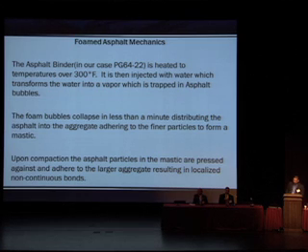Okay, so foamed asphalt mechanics. The way it works is your transport truck comes in with your PG binder, in our case 64-22. It comes in at above 300. Temperature varies. In this case, it was 325. We test the foam bubbles, just like I mentioned. Test your expansion rate, test your half-life, and then these particles are compacted, pressed, and adhere to larger aggregates, resulting in localized non-continuous bonds.